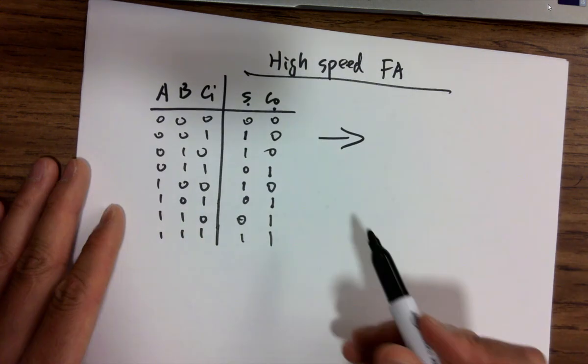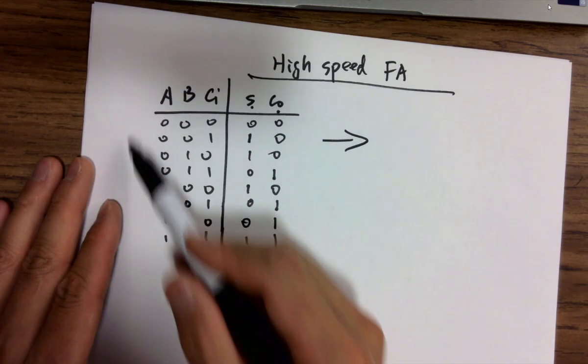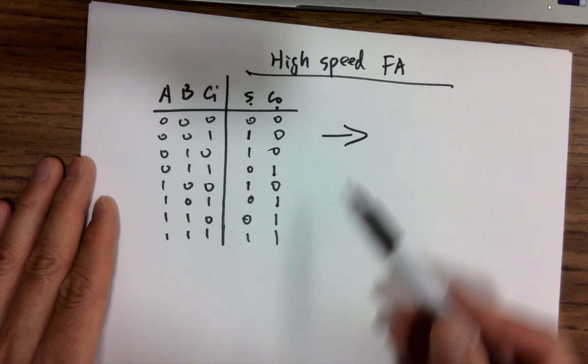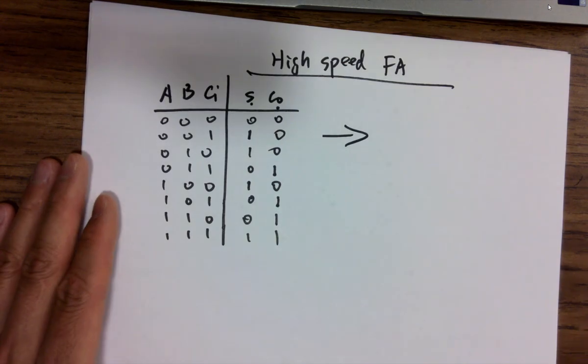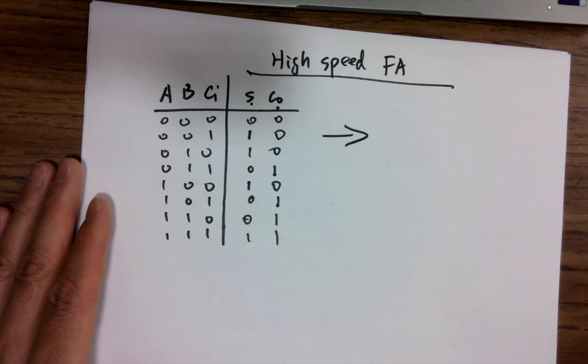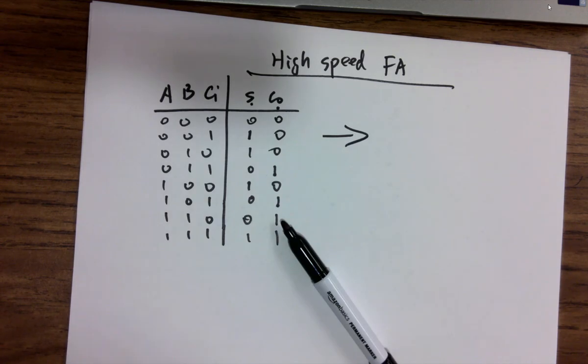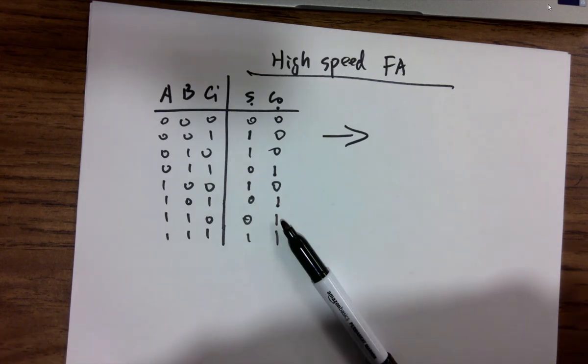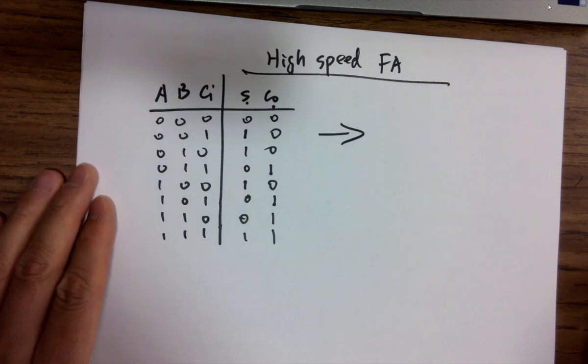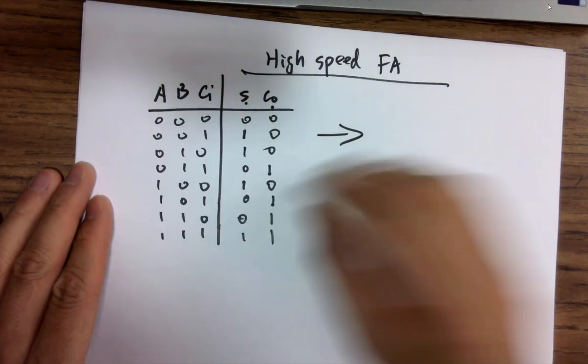The goal is to go from what we need to a physical circuit. The deliverable will be a physical circuit. For us, the physical circuit will be a schematic and layout, because if we know the schematic and layout, we can just put it in Electric VLSI, draw the layout and send it to a foundry to fabricate it. That's the final deliverable. It's done, right?